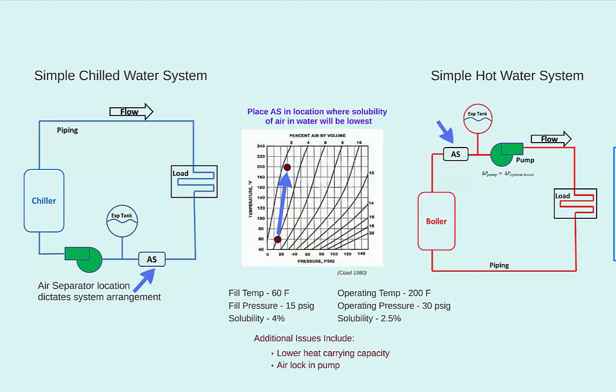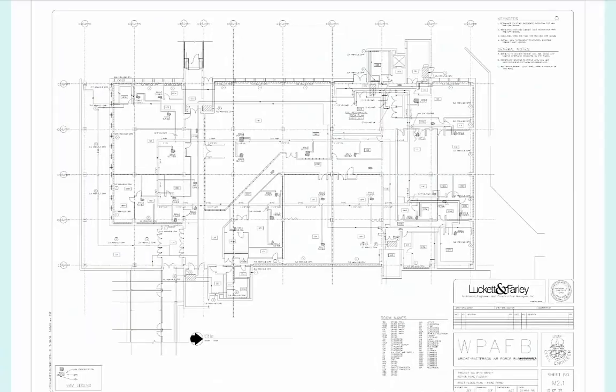We can't afford to dive too deep into drawings, but we think it is important to at least tell you where some of the information you may want to find would be located in them. First off, the general layout of the hydronic system usually has its own dedicated drawing in the set of as-built drawings. For larger buildings, there may be one such drawing for each floor or wing of a building. This drawing is often called the HVAC piping plan or just piping plan. It will be in the mechanical section of the drawing set. Thus, its drawing number will have an M in front of it.